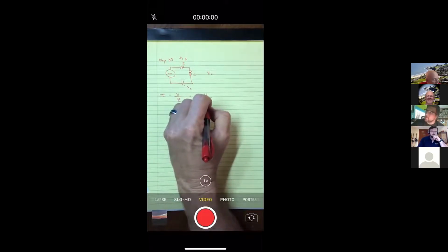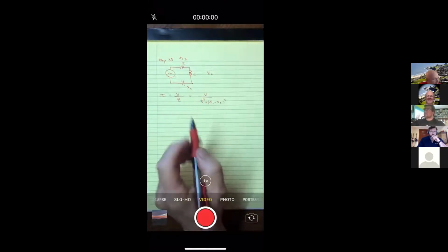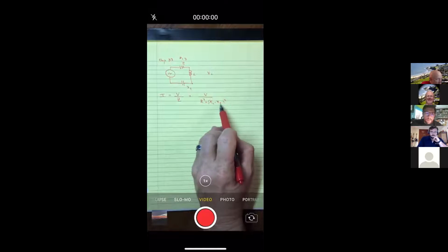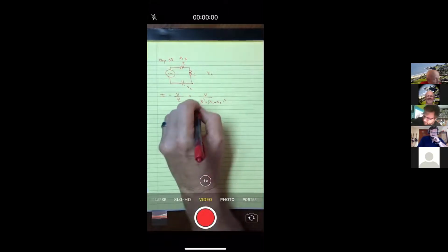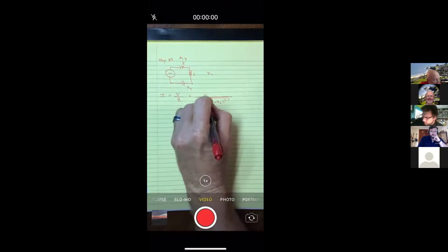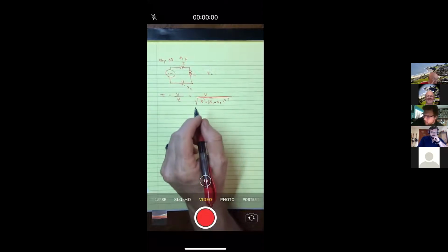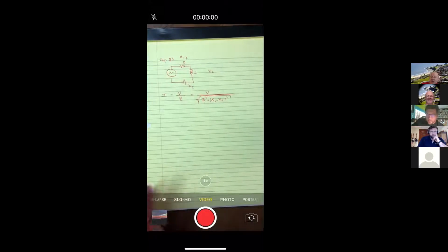But we did go through a little phasor diagram and come up with the fact that the reactances of the inductor and the capacitor are opposite of each other. So you subtract the two, and they're at 90 degrees in terms of a phasor diagram. So when you combine the effect of resistance and reactance, we call it impedance, but to get the total, you have to add them like you would two vectors at right angles to each other. So you have to do a Pythagorean theorem. We call this addition in quadrature. So we've got to add the effect of all of them.